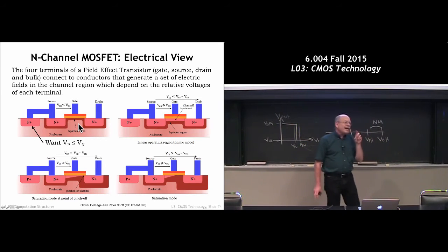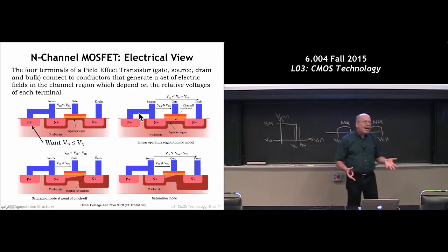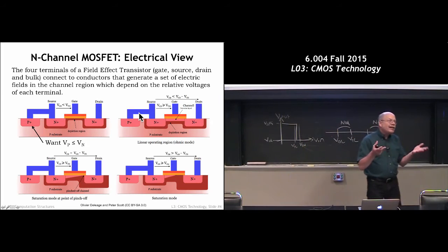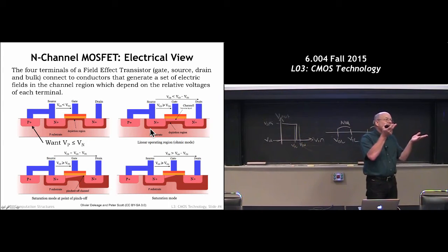Eventually, in a seemingly instantaneous switch, although if you look really closely it's exponential, once I get a certain voltage, right around half a volt, I suddenly am sucking all these electrons out of the valence band of the material in the substrate and moving them into the conduction band. So I'm creating mobile carriers by putting an electric field across the device.